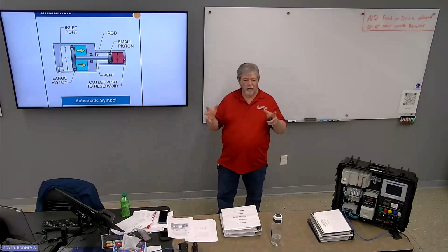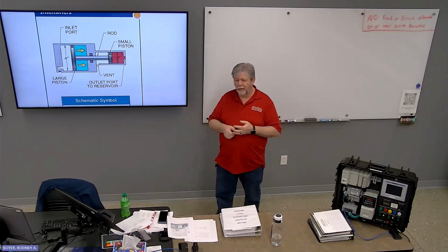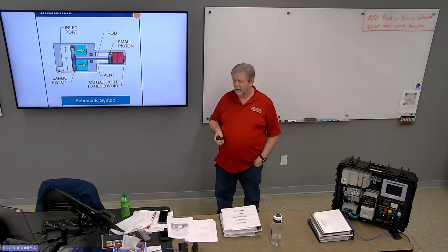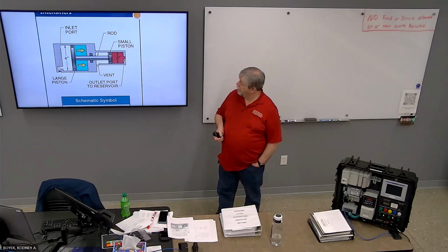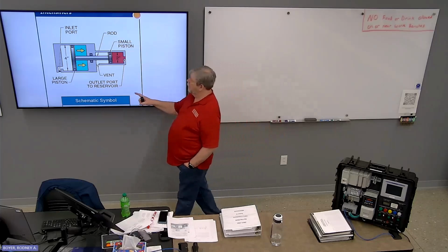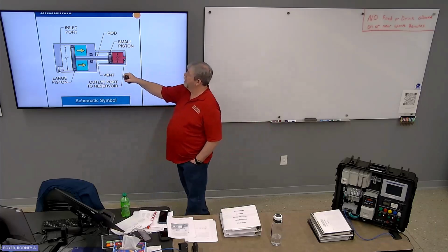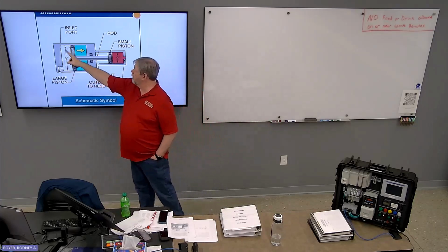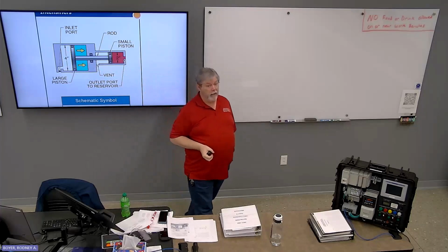Okay, there's no connection between the low pressure or the large side and the high pressure low side. But as you are applying pressure here, it's transferred through and it's putting all the force here in this little bitty area, which causes a dramatic increase in pressure.